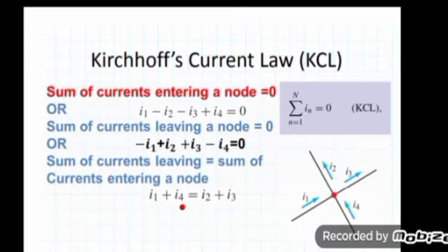So this is Kirchhoff's current law, and this law will be definitely helpful for you if you really want to find the desired value in any electrical network, or just want to solve any electrical network analysis. At every node you have to apply Kirchhoff's current law. That is a very important formula, and a very important law conceptually, if you really want to solve any tricky network. And this is the expression for n branches, where the nth currents are incoming and outgoing. Same concept we have to apply here according to this formula.